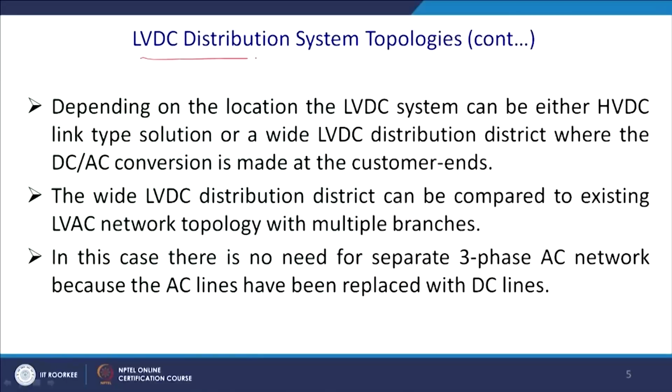LVDC distribution system topologies, depending on the location of the DC-AC conversion, can be either LVDC link kind of solutions or a wide LVDC distribution district, where the DC-AC conversion is made at the consumer end. That is something we require to understand.